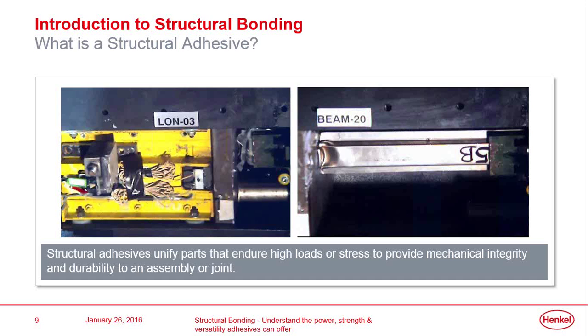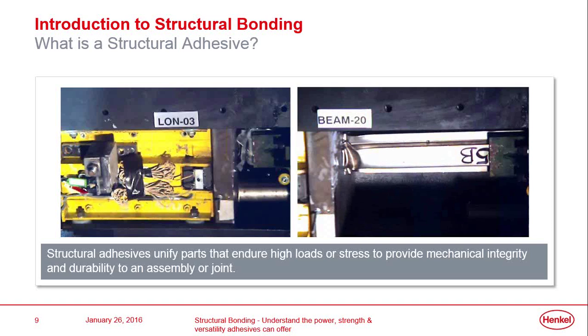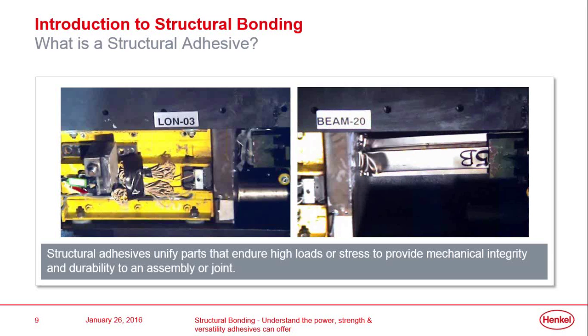And that's because all of these flanges are contributing, because we have adhesive on the whole flange area, all of that is contributing to the resistance of this impact test. And if I run the same sequence through, here you can see that we get a nice uniform folding of this beam, not this catastrophic bending and catastrophic failure.